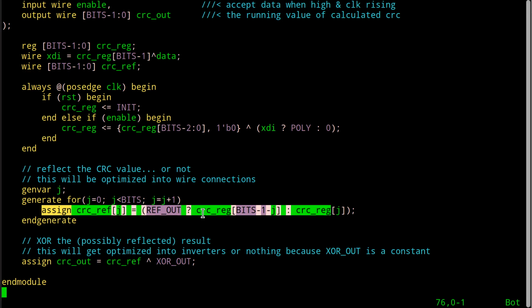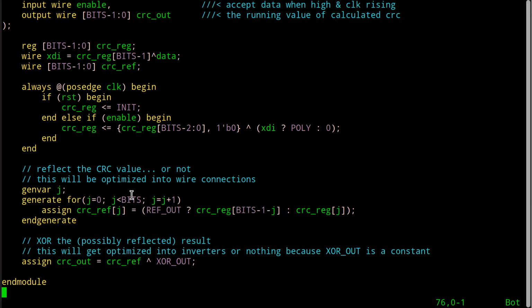That makes sense. So I've got to write a for loop going from 0 to whatever n is, and that'll be 8 or 16 as the case is in the two test benches. After each pass I'm going to add 1 to j. And for some reason, in the infinite wisdom of the designers of Verilog, I cannot say ++j nor j++.